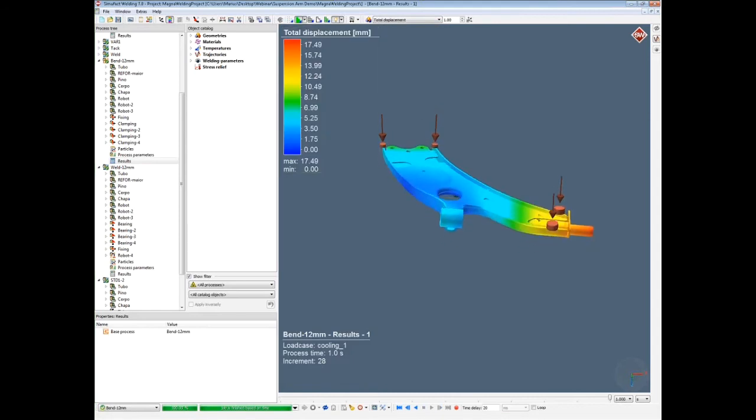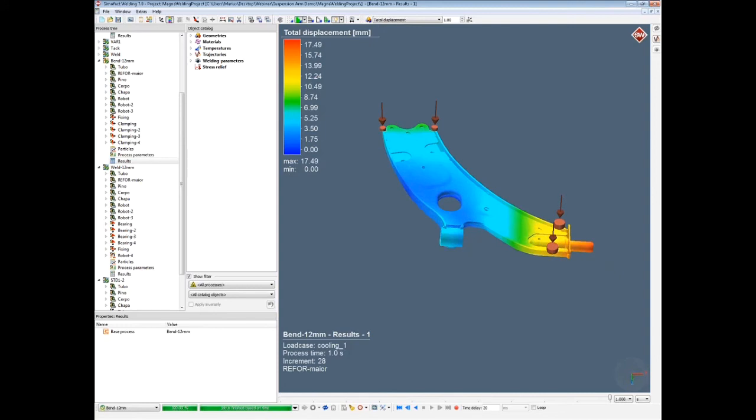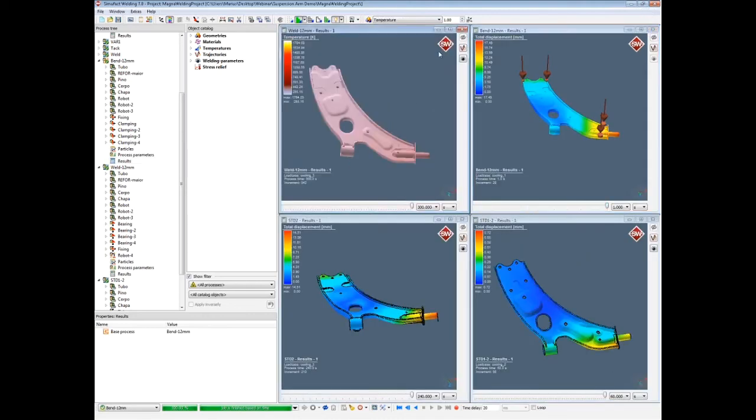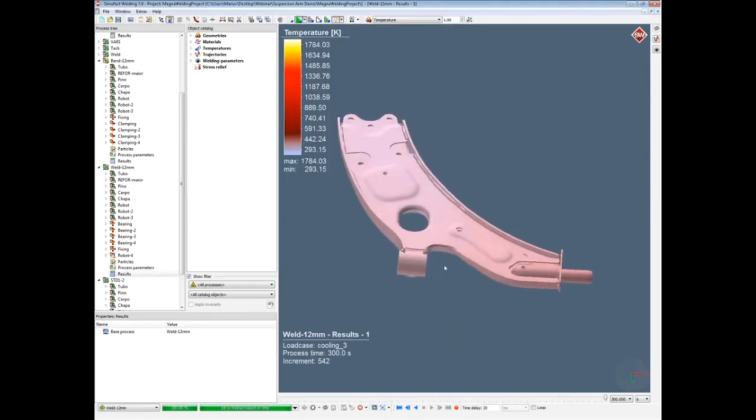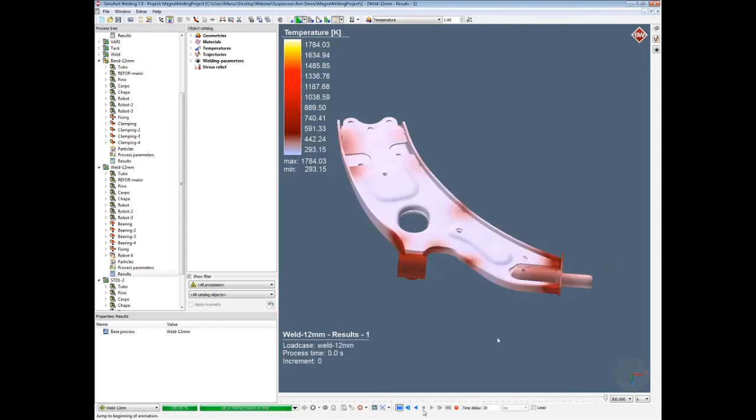Because the idea behind it is if we then weld along this line, the shrinkage of the weld seam will then increase distortion in the minus direction, upward, and then we will end up with a fine distortion distribution. And this is what they got after this.